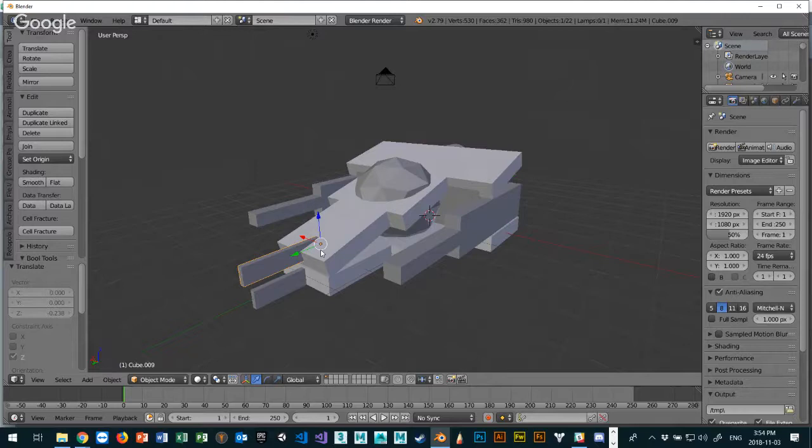Okay, try moving that around. So try pressing the G key to move it around. So undo, press escape. So Shift right click the other part. Shift right click. Good. And Shift right click that part. Good. Now press G. Okay, and you can use numeric transforms that way too.